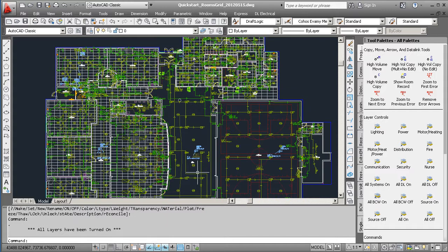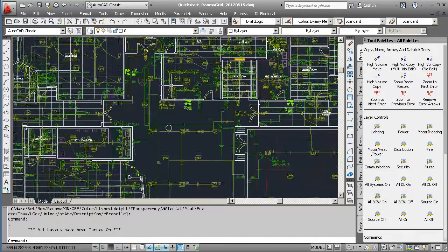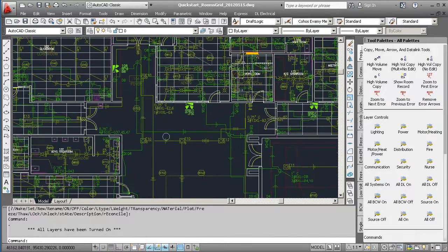So there we have branch circuit wiring. The lighting, receptacle, and motor systems are all automatically handled. Other systems, like for example emergency floodlights for now, communications and other low volt type systems, and fire systems, you'll need to manually draw your branch circuit wiring or use whatever processes you currently use. If you use DraftLogic Electrical's layering and the branch circuit wire manager to populate the information on the lines, then the bill of materials and ConEst export to IntelliBid will capture that information for you.